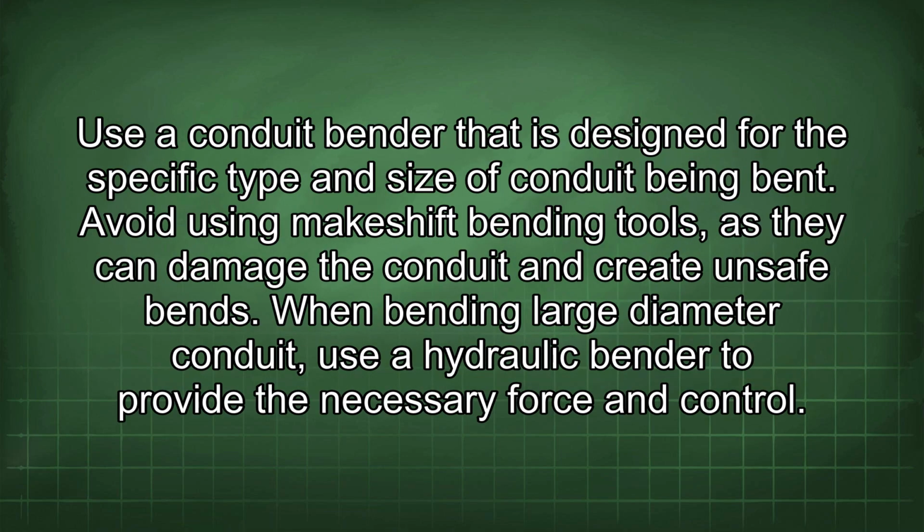Use a conduit bender that is designed for the specific type and size of conduit being bent. Avoid using makeshift bending tools, as they can damage the conduit and create unsafe bends. When bending large diameter conduit, use a hydraulic bender to provide the necessary force and control.